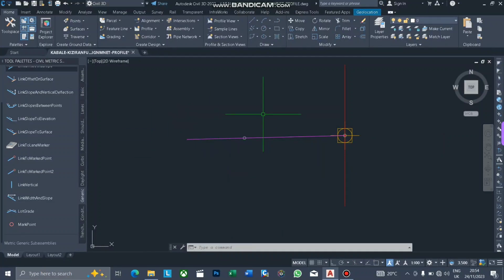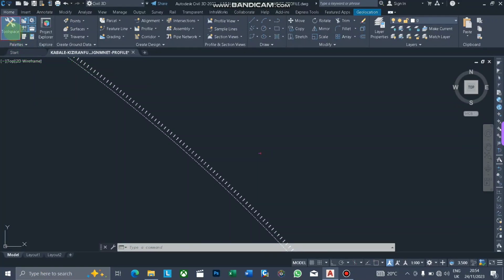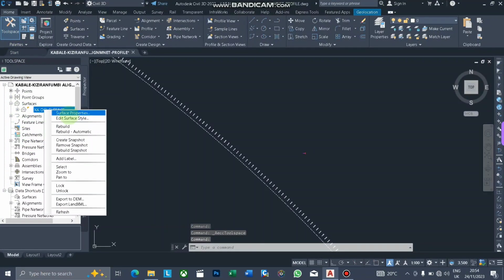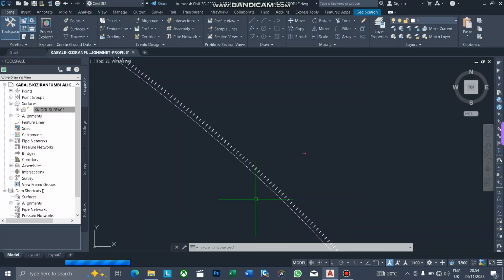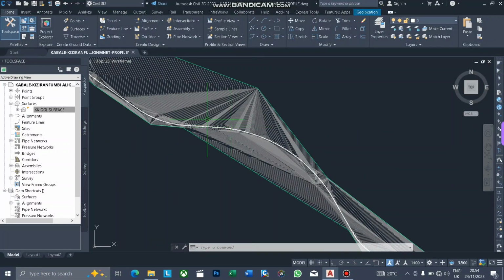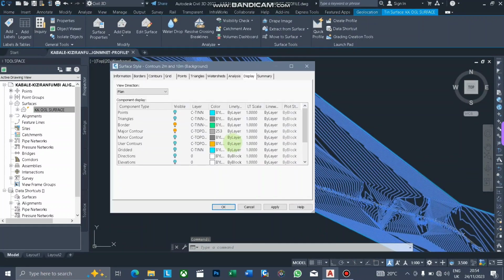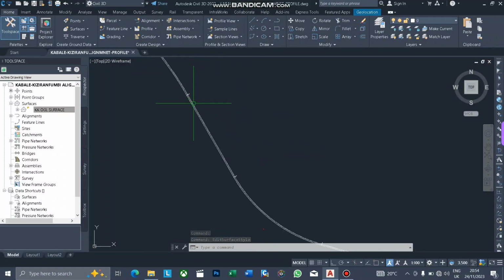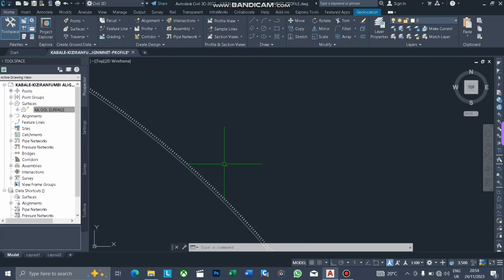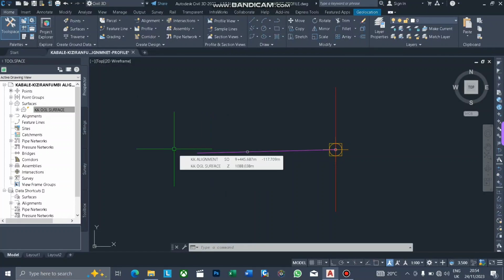So the road alignment you see here goes through regions of cut and fill, as I will show you here in our surface. I'll turn it on, and you can see the mountainous sections, the valley sections. So the alignment goes through all those regions. I'll turn it off, and then in order to have a ditch maybe in a cut section, or to have no ditch in the fill section, is determined by the conditional subassembly.